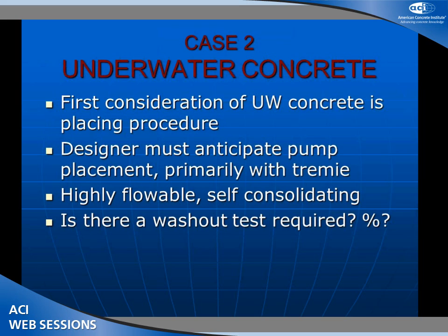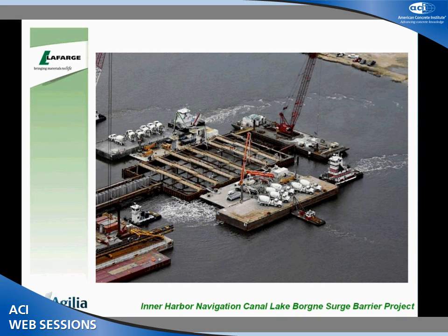Primarily tremies. The Corps of Engineers does require tremie placement. They don't want to allow just a flat pumping. We want highly flowable concrete because we're not going to be able to have someone there handling that boom, placing it right where it needs to be, so it needs to flow to limit that. You've got to keep the tip down in there. So a lot of these challenges. And then, is there a washout test to determine that this concrete really is underwater capable or not?